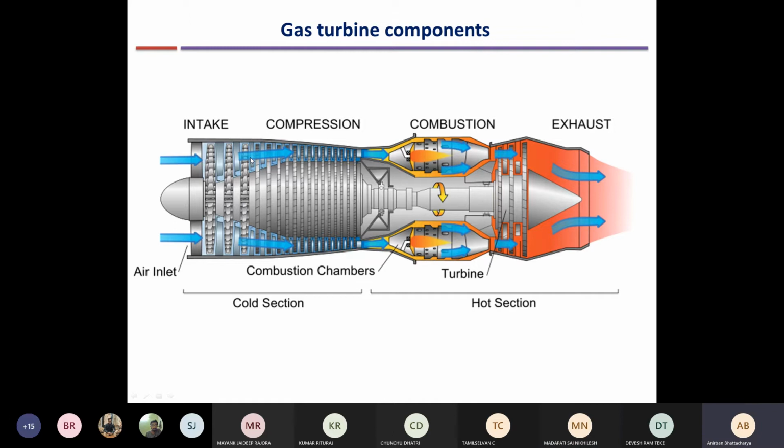If it is an ideal steam turbine, or a gas turbine, it's an isentropic process. If there are losses, then the entropy can increase, but still it will be an adiabatic process. Losses means frictional losses inside. If we ignore the frictional losses inside, it will be an isentropic process. So the process in the turbine is known as isentropic expansion, because the pressure is reduced. The process in the compressor is isentropic compression, similar to a pump.